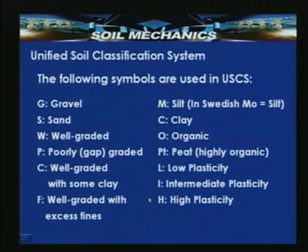Suppose you find a gravel well graded with excess fines, that type of soil predominantly behaves like a clay soil, because the fines present in between gravel particles will not allow the gravels to come closer, and finally they inhibit mobilizing the strength.